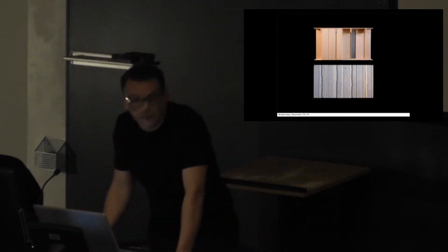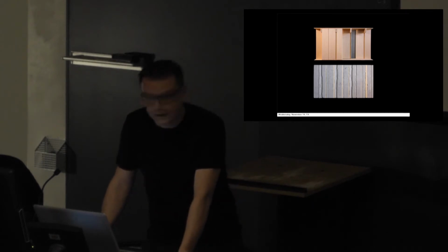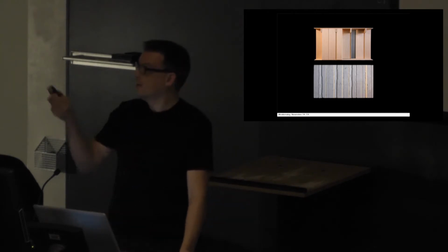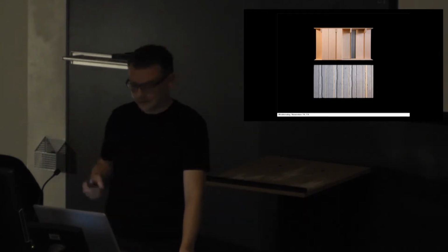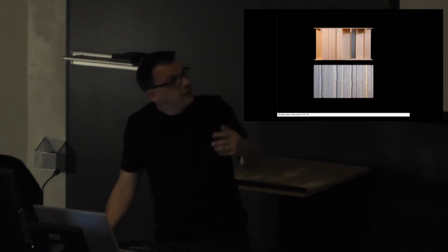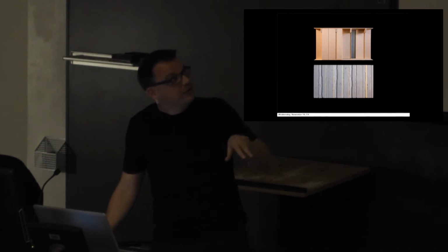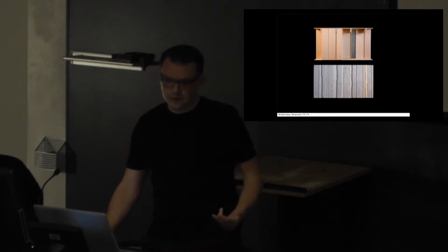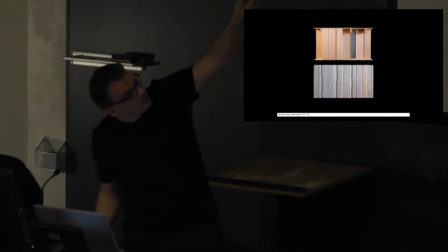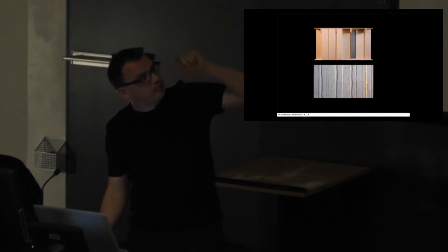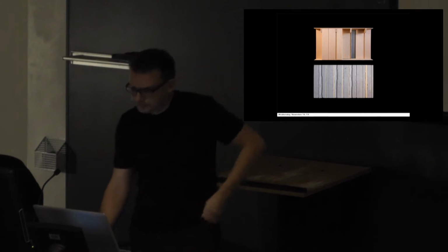The inside of the house follows the rhythm of the exposed structure. The entire level is actually clad in clear-sealed MDF panels, which is really the same as what you see here in this auditorium. And these MDF panels were installed with a reveal between them to sort of mark the occurrence of the structural grid, which is 48 inches on center. As you can see these lines from the floor, from the roof beam sort of reading through.